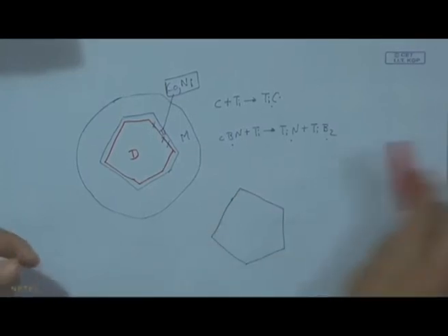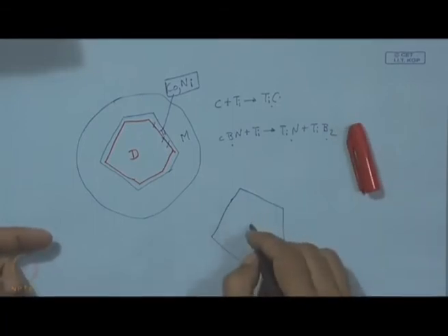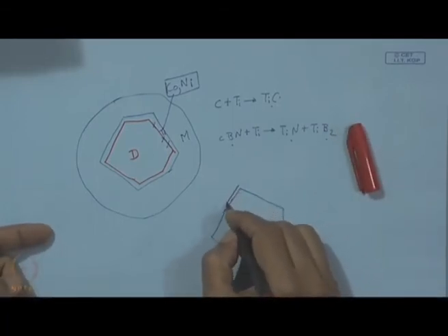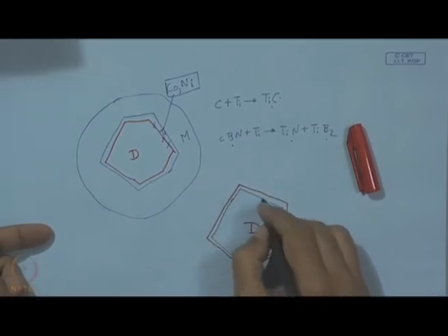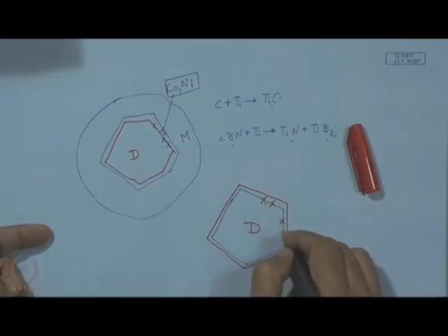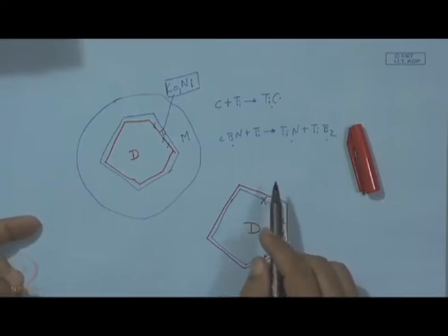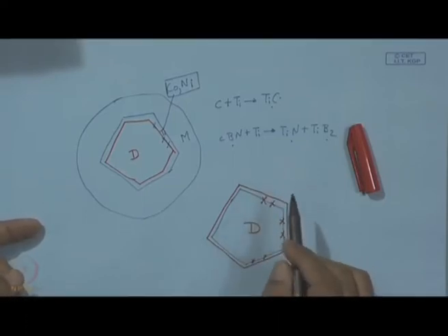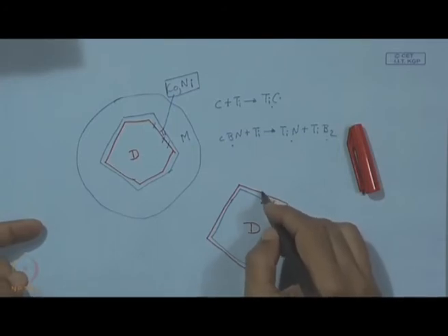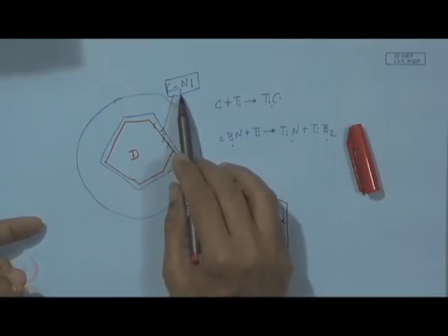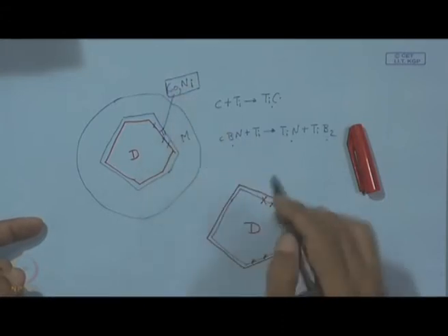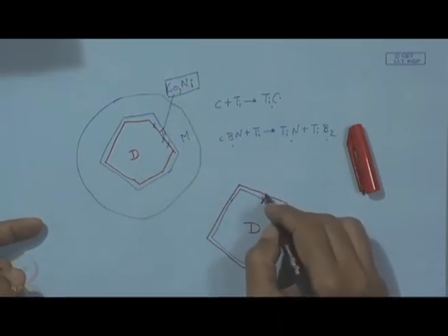Now, in this connection it can be said further that if this is the diamond grit, then we have a primary coating of titanium which has a chemical bond with diamond. However, it is seen that this titanium is actually prone to oxidation. So, if we have a titanium oxide on the outer surface, then this oxide may not facilitate bond formation with conventional metal binder. So, this surface is chemically attached.